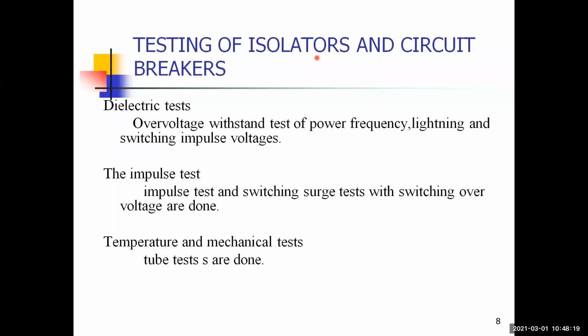So, the dielectric test: we have to do the over voltage withstand test, with power frequency, lightning and switching impulse voltages. So these are the different types of voltages, and the over voltage withstand test is done with power frequency, lightning and switching impulse voltages. These voltages are very high, in the range of kilovolts or even megavolts.